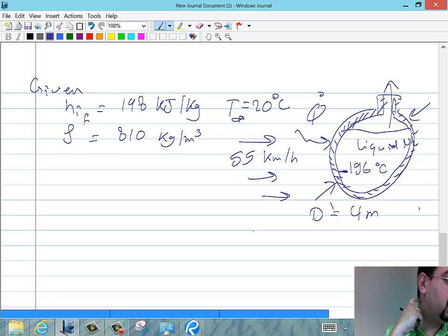The temperature of the thin-shell metallic spherical tank is observed to be almost at the same temperature as the nitrogen inside. Because the tank is really very thin, and say it's made out of metal, if the temperature here is Ts, the temperature here is also Ts. How come? Well, the conductivity is pretty good, and therefore the resistance to conduction, which if you remember was R2 minus R1 over 4 pi K for a sphere, is really tiny. So the temperature is almost the same from both sides.